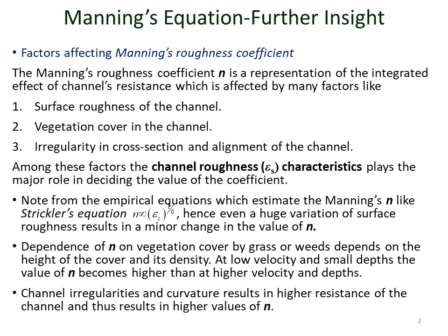The Manning's roughness coefficient is a representation of the integrated effect of the channel's resistance. So it's representative of the channel roughness, and it's affected by factors like the surface roughness of the channel, the vegetation cover in the channel, the irregularity in the channel cross section, and the alignment of the channel.